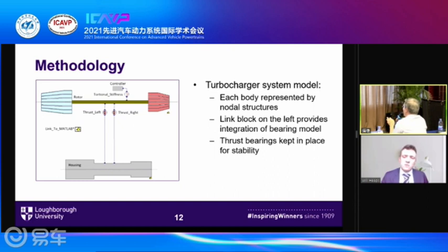All right. Now, I can see your result. If you assume the rotor shaft as a rigid body, then you only get a resonance frequency almost fixed. But once you assume the shaft is a flexible body, then you do get the so-called critical speed. That's different from the normal resonance frequency, because critical speed is associated with your rotating speed. That's why you also have some nonlinear effect there.